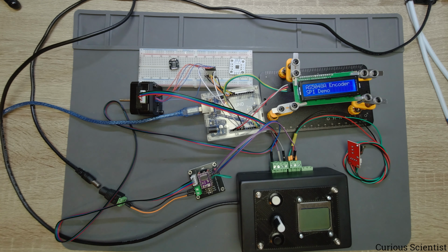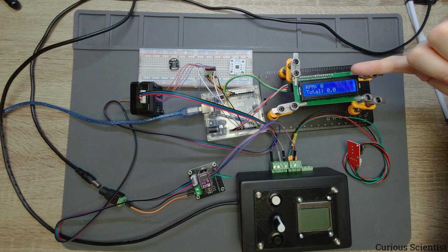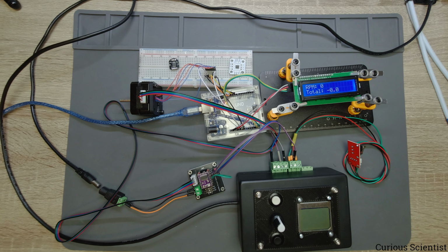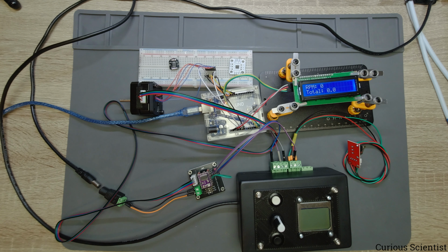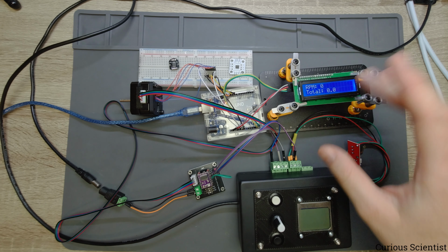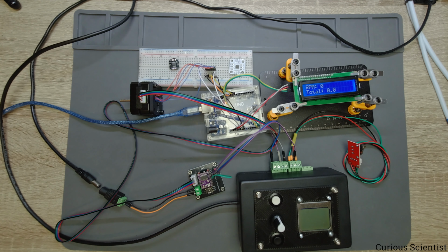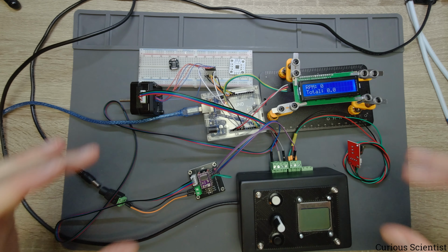So now I plugged in this part, the top row, which is just the magnetic encoder. And what you can see is that the RPM is 0 because the shaft is standing still. And this is the total angular displacement. There is always some small uncertainty in the angle that we read, so that's why this number is sometimes jumping between 0, minus 0.1 or plus 0.1. But that has nothing to do with the device. It works nicely. So this is fixed.